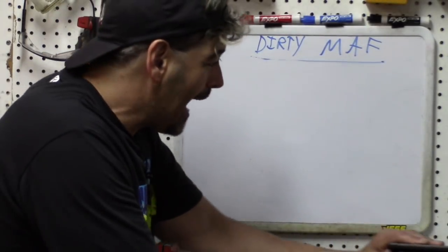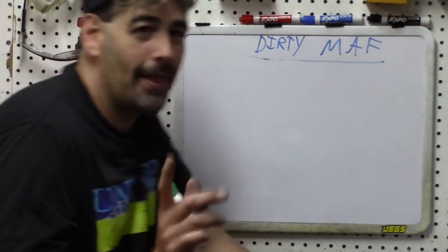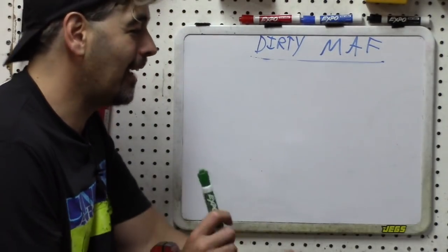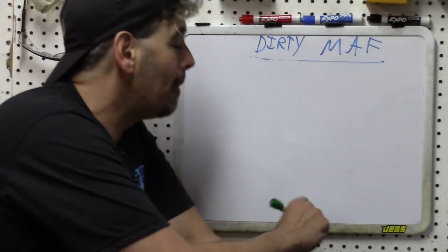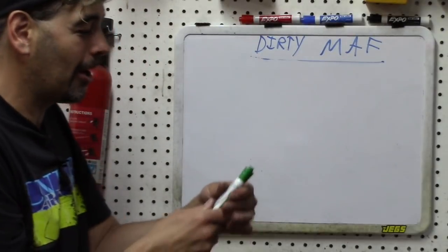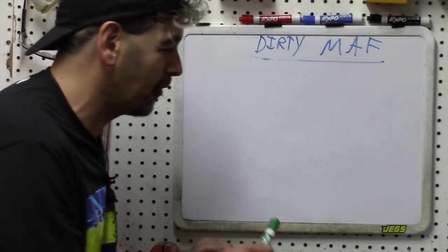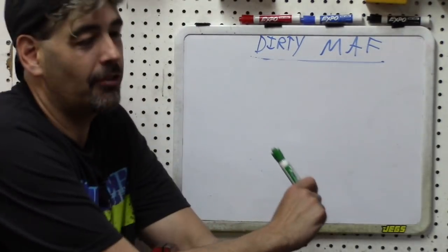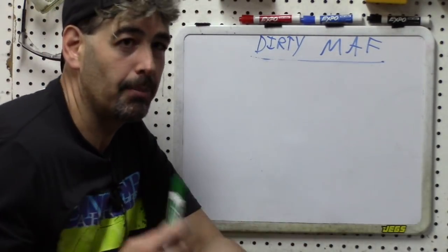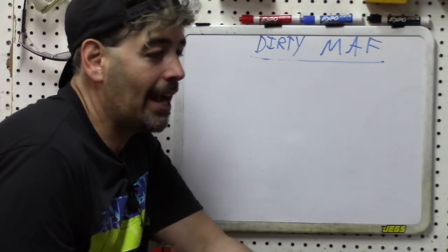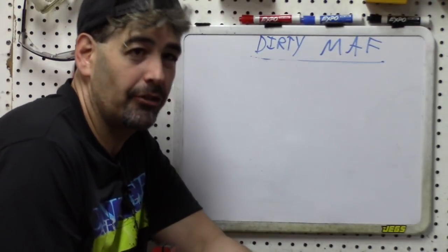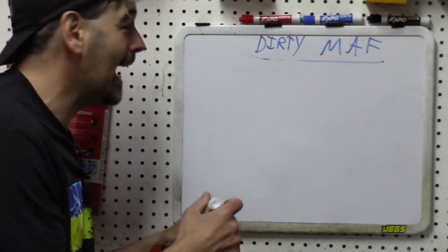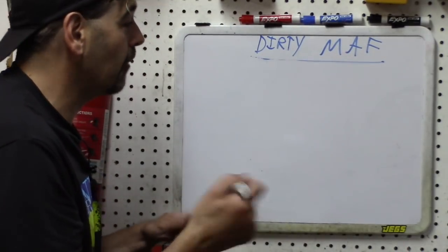Okay, and with that, I will actually tell you that on that same car was actually one of my very few diagnostic failures. But what actually happened on that car, everybody loves to hear about other people's failures. It was very obvious to me that that was a mass airflow sensor problem on that car. So I diagnosed dirty mass airflow sensor as being the likely issue, and I went ahead and cleaned the mass airflow sensor.